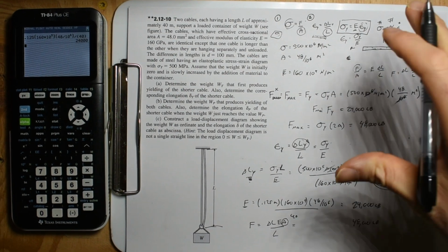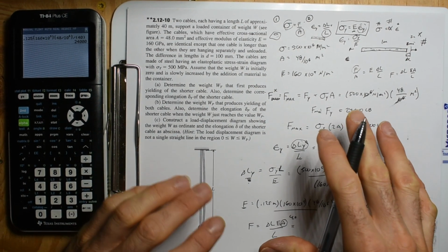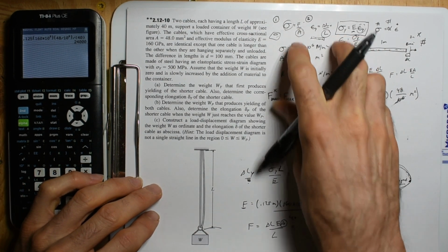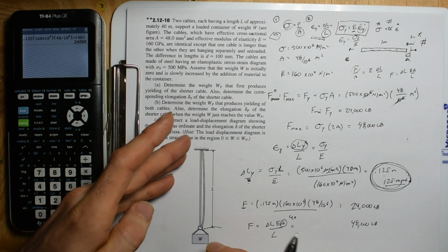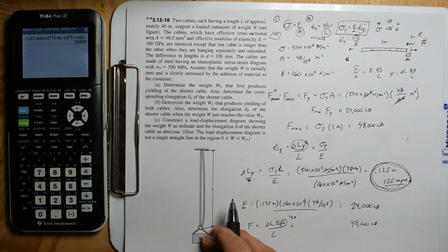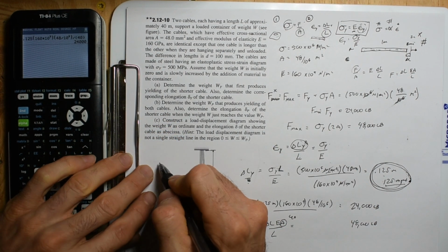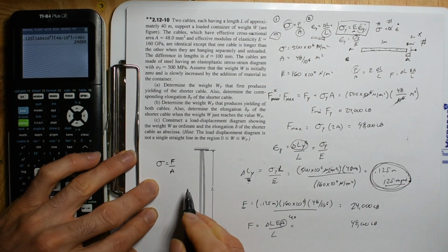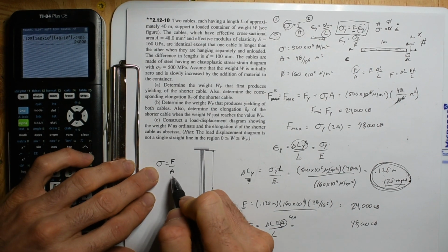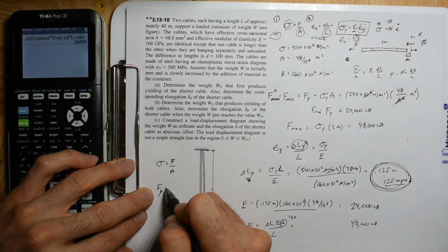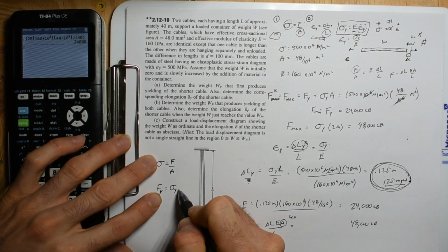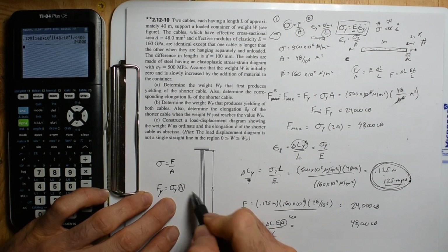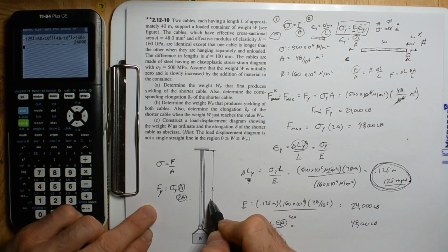But yeah, and I guess that's it. You know what I mean? That was at least within 10 minutes of just using these two equations, throwing it at the problem, and being like, oh yeah, so I can actually figure out, because I solved this and I didn't use this. I didn't say max strength is force over area, and just rearrange and find that force of yield. Force of yield is the yield stress times the area. And I could have done that right off the bat and done it for one rope or 2 times the area and done it for 2 ropes.